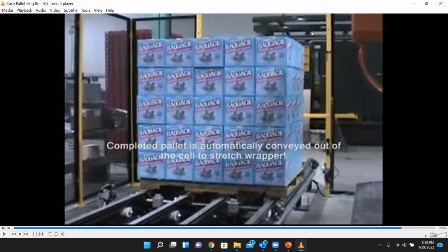So as engineers, technical people, you need to identify the task in individual activities, right? That is how you design solutions, right? So in order to handle the pallet, then to pick and place the boxes, and then place the board, if you can have one single end effector with different parts that you can use for various activities, you can use one robot with a 3-in-1 end effector. Okay, so what you need is a 3-in-1 end effector and one robot. If not, you can have a 2-in-1 end effector and another manipulator, another arm with another end effector to do the operation. So two arms will do the operation.